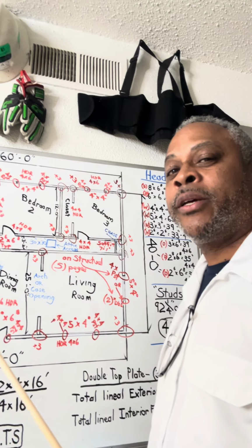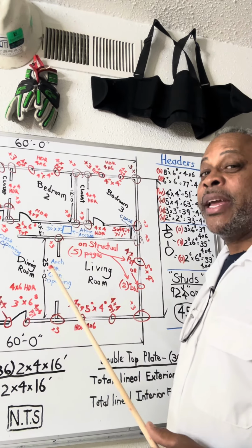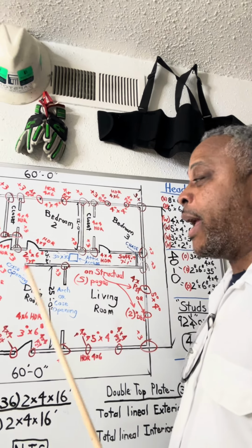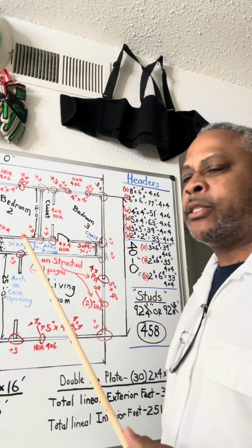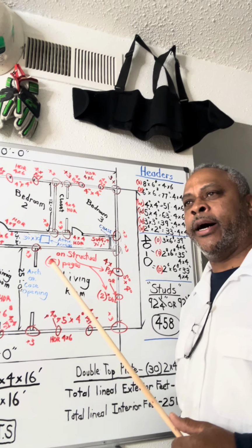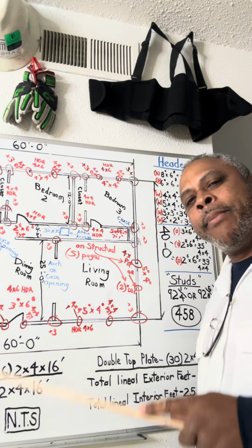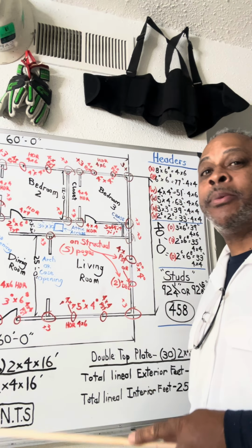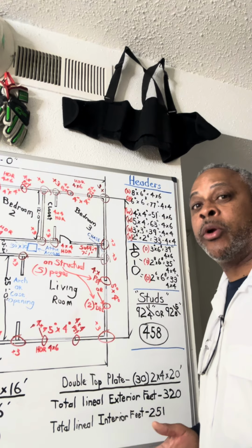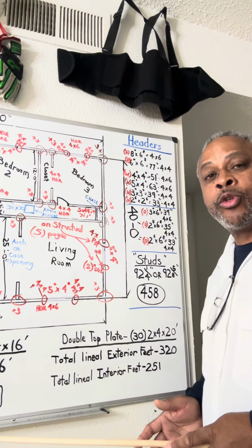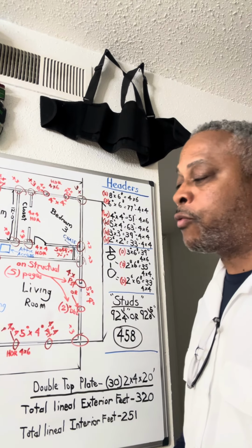Anywhere past 4 foot, 4x6. When it gets past 6 foot, it's 4x8, and so on and so forth. And those header sizes, LA has a Type 5 sheet. You can go online to the LA Building Department and look up the Type 5 sheet. It gives you the minimum qualification standards of lumber sizes and lumber spans on different parts of wood and lumber, from floor joists to ceiling joists to stud heights, underground heights for your crawl spaces for a raised foundation.